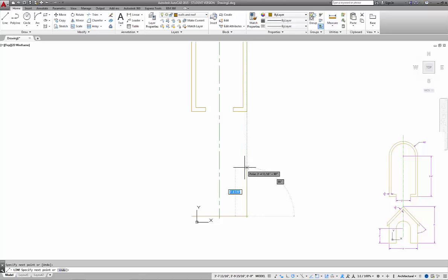To do that, I can create a box that's 5 foot. So I'm going to draw 5 feet straight up. Come how far over? 4 feet. So instead of projection, I'm just going to type it in. 4 feet over. And it better line up and produce a nice little rectangle for us here. And to stop the line, I'm going to choose enter.